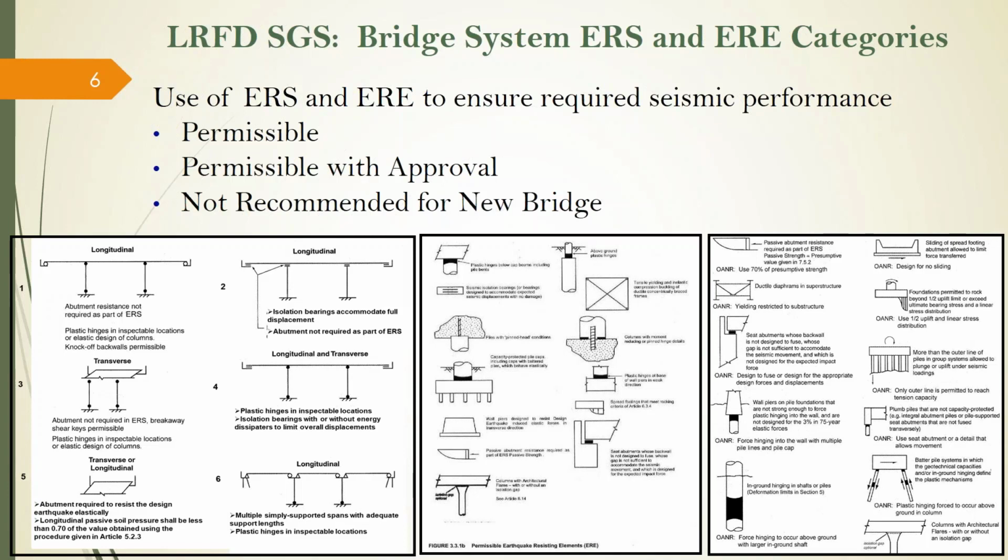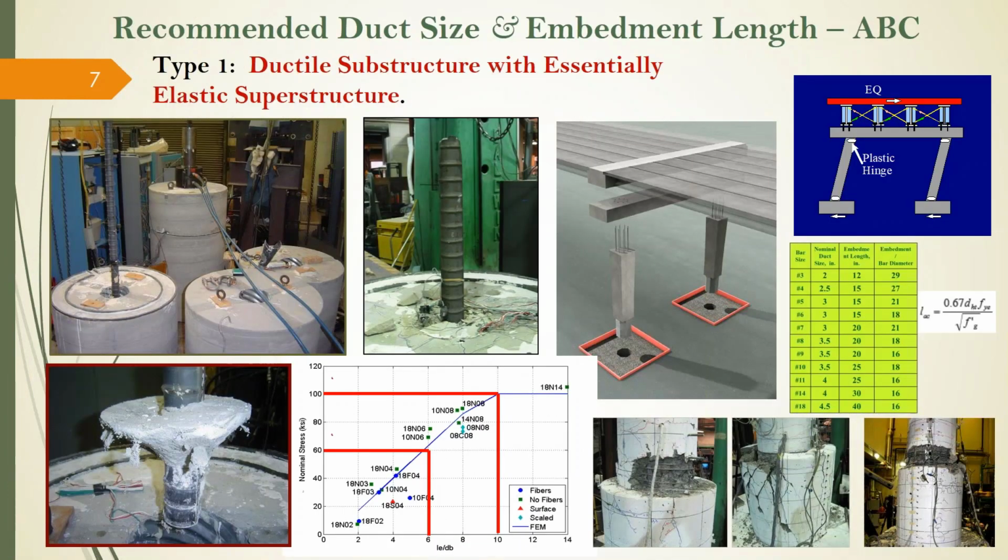In order to get to seismic resiliency and also meet the ABC requirements, the very first step that we did in Washington was doing some precast connections. We started with the grouted duct connection by University of Washington, Dr. Stanton and his team.